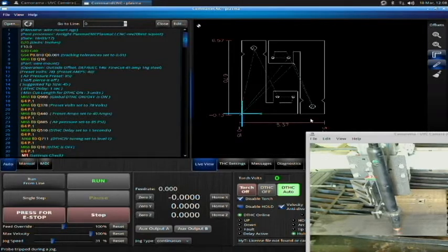So in this video we're going to be discussing navigating the G-code and fixing errors during a cut. I have positioned my plate and zeroed out, setting my job zero, and I've also clicked the disable torch button, because initially while we work on this, we're going to be doing dry runs so the machine is not cutting. Okay.